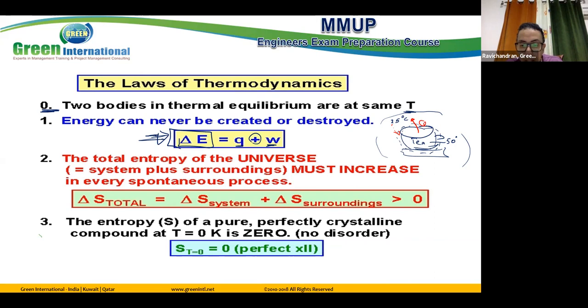Okay. So if you're going from state 1 to state 2, we have an energy change due to entropy. Whatever heat and work happen, but also entropy. For example, flow goes through a throttling device, like a porous plate with holes, and the flow comes in with high pressure. After this porous plate, its pressure is down. What happened? Entropy increases when you go through this porous plate.